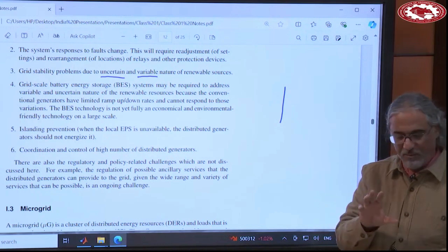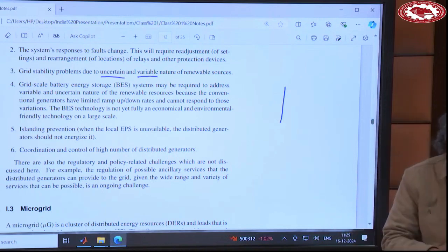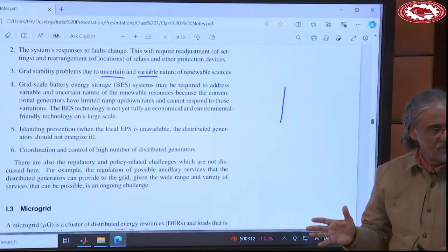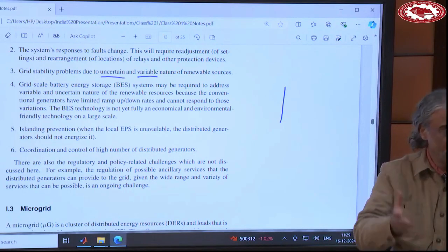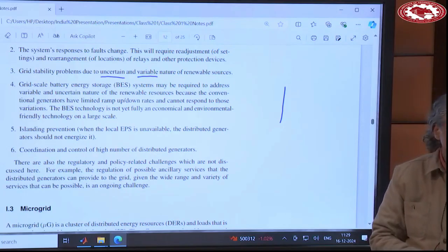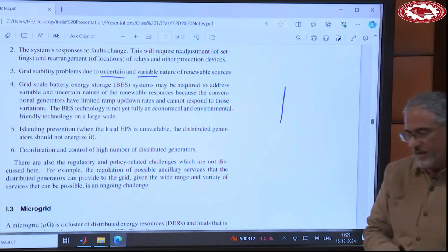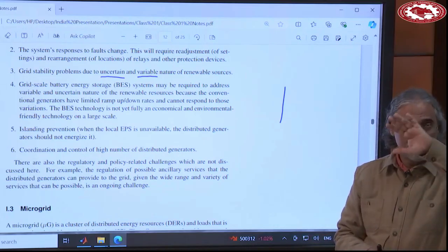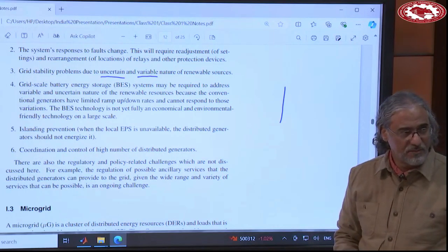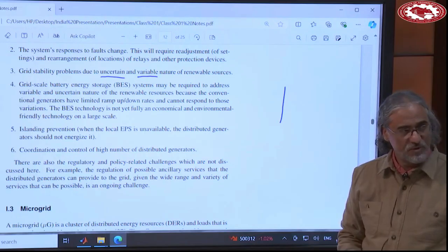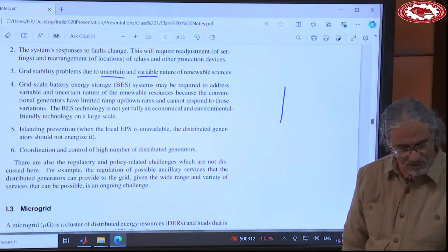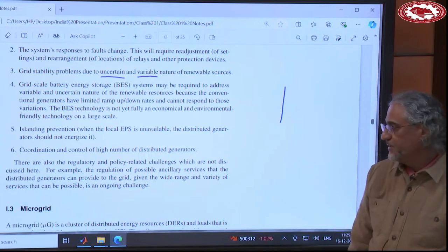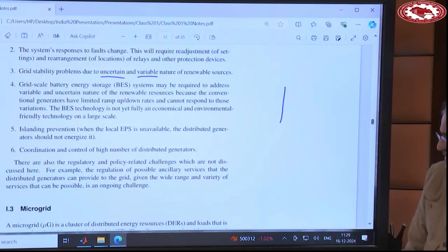Let's say part of the power system is going through a problem. In the conventional power system, when you have unidirectional flow, the protection device opens, or you open that part of the circuit, and then you go there and fix the problem. Right? But now, even if that switch opens this part of the distribution system which is under fault, you don't want some of these generators to keep powering it, for the sake of safety of the people who are working on that part.